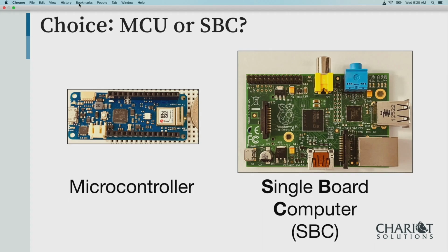But because of that, you can buy some of these. They have a real-time clock in some cases. You just say, go to sleep for an hour, and when you wake up, resume what you're doing. And when you're done with the cycle, the loop of reading everything and sending it up, go to sleep again. Wake up in another hour, and so on. And that takes a lot less power, especially if the radio is turned off until you wake up.